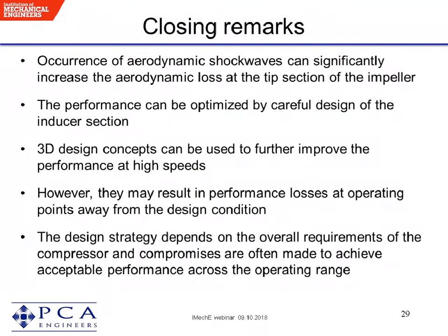This brings me to the closing remarks. The occurrence of aerodynamic shock waves can significantly increase the aerodynamic loss at the tip section of the impellers, and for transonic impellers, the performance can be optimized by careful design of the inducer section.